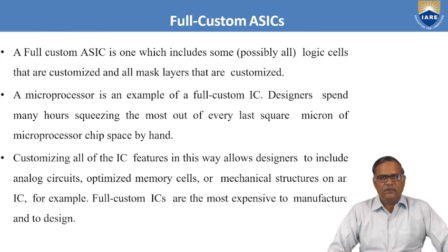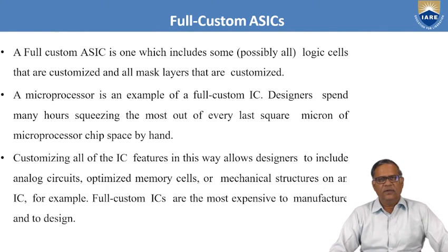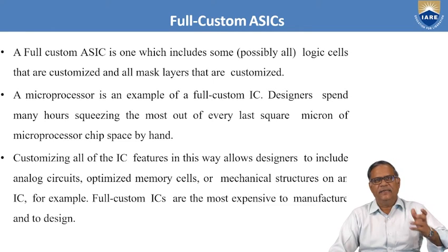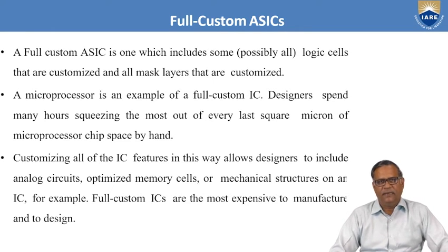Now let us discuss full custom ASICs. A full custom ASIC includes some logic cells that are customized, and all mask layers are customized. So all the design is done by the designer. He does the work from scratch. He does not take standard cells or standard libraries from anywhere. He does everything on his own. A microprocessor is an example of a full custom design.